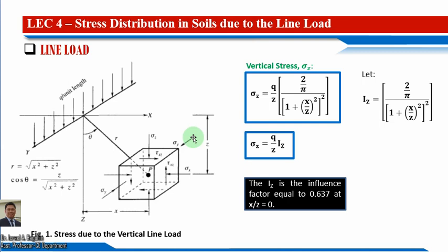Based on the illustration, the basic equation used for computing the vertical stress at any point P in an elastic semi-infinite mass is Boussinesq's formula. By applying the principle of his theory, the stresses at any point in the mass due to a line load Q over unit length of infinite extent acting at the surface may be obtained. The state of stress encountered in this case is that of a plane strain condition.